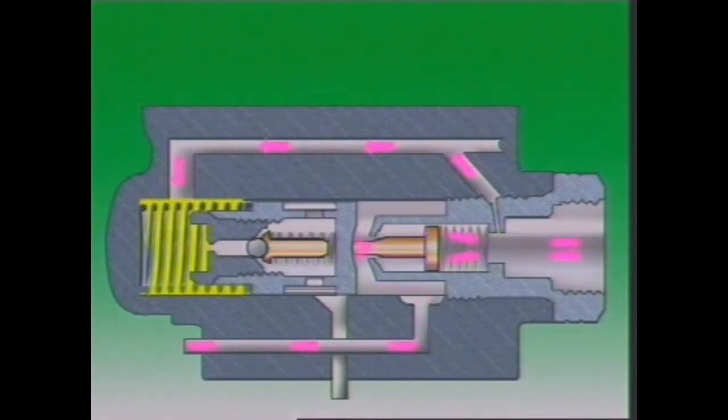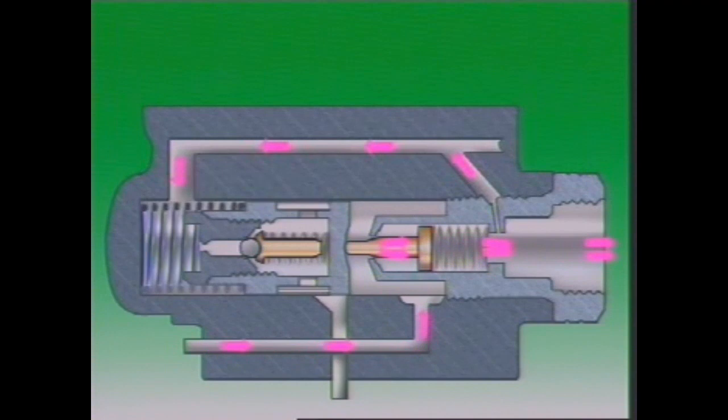This lower pressure is transmitted through a bypass fluid passage to the spring end of the control valve. The pressure difference on the valve causes it to move away from the outlet fitting, but the force of the spring prevents it moving far enough to uncover a return port back to the pump inlet. Movement of the control valve controls the position of the needle valve in the outlet fitting, and this controls the fluid flow to the steering gear.